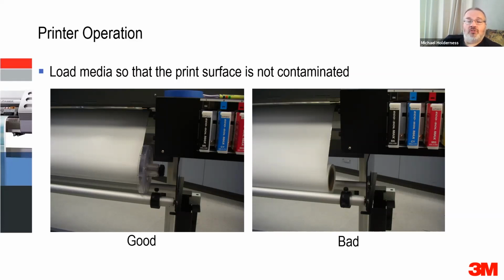You want to make sure that the roll is not sitting on a surface or picking up dust from somewhere. A number of the more modern printers will have covers over the back so that you don't end up with the contamination that print shop got with the silicon from their neighbor. So those sort of things, as time goes on, we are trying to get around a lot of those issues, and a lot of those issues are being solved by the companies that make printers.